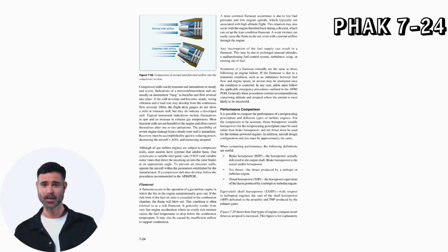Flameout. A flameout occurs in the operation of a gas turbine engine in which the fire in the engine unintentionally goes out. If the rich limit of the fuel-air ratio is exceeded in the combustion chamber, the flame will blow out. This condition is often referred to as a rich flameout. It generally results from very fast engine acceleration, where an overly rich mixture causes the fuel temperature to drop below the combustion temperature. It may also be caused by insufficient airflow to support combustion.